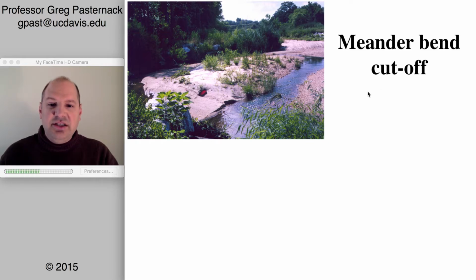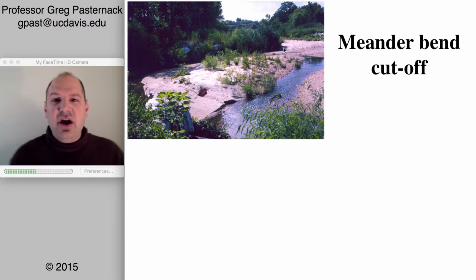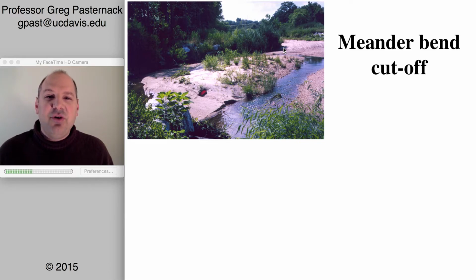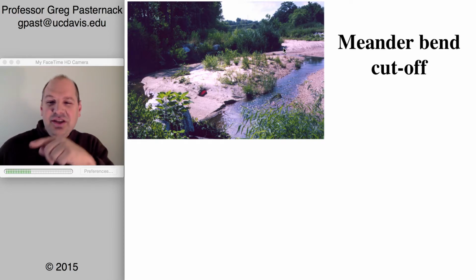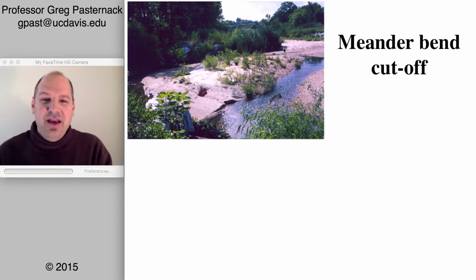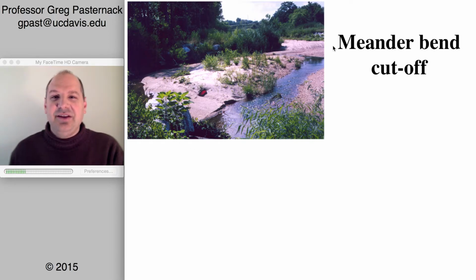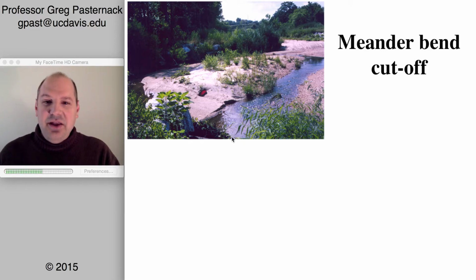Another thing that we saw is systematic meander bend cutoff throughout the whole river corridor. The reason for that is because, of course, there's no function in geomorphology that tells us what the meanders should be. Should it be a sine function? Should it be a sinusoidal function? Should it be some sort of noise function like Perlin noise, or who knows what? What should the shape of a meander look like? And so they just made them generally sinusoidal for lack of anything else. But the river's like, nah, I don't like that. I'm just going to cut all that off and go my own way, in general going straight.